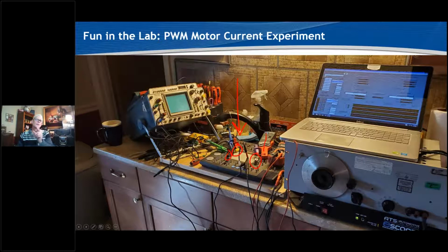width modulation. Now, what was really interesting about this was we were studying diodes and their effect on flyback voltage. And when you see the next couple slides that were born out of this experiment, you can really easily see how pulse width modulated power control circuits can reflect back and destroy a driver very quickly. What we're doing in this case is we're driving this signal with an audio generator, an audio oscillator, and then we're changing the resistance on these little slide switches or round switches here to make the circuit run faster or slower. Really cool little experiment to set up.